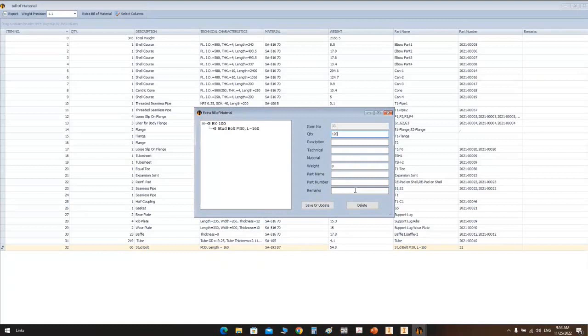After making the tie rod, inshallah, the next step after adding this nut on the SEG bill of material is that we will proceed with the tie rods. We have two different lengths for tie rod. After adding them, we will add the spacers, and we will make Autodesk Inventor calculate the required number of spacers and get a separate bill of material for the spacers with the lengths. Is that okay?